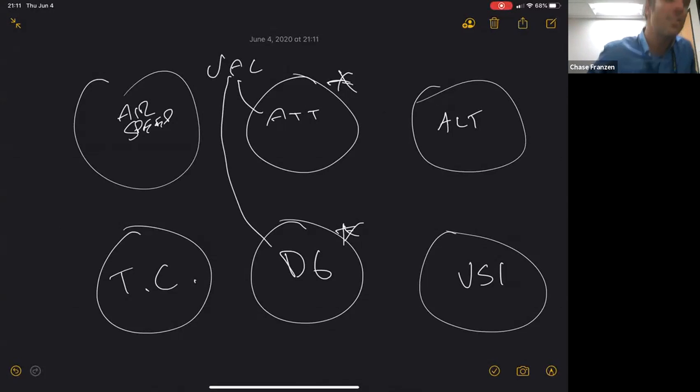And I'm going to explain a gyroscope, or a gyro, in a minute here, but I like to think of those gyros as having, do you remember the boats that had the paddle wheel on the back? I like to imagine on the back of those gyros, there's like a paddle wheel on them. And so as you are creating negative pressure in the vacuum system, it's sucking air through the paddle wheel, and the paddle wheel is spinning the gyro very, very quickly.